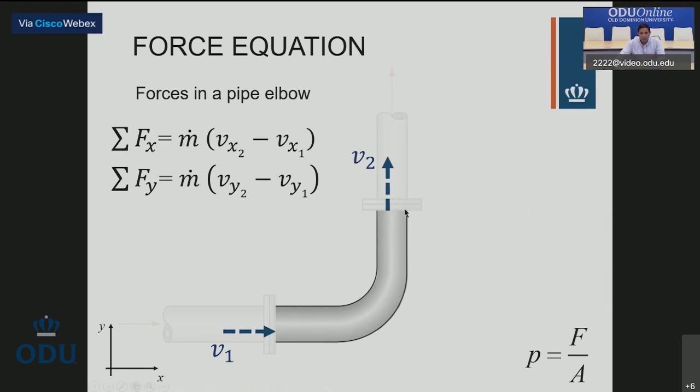And if there is pressure, there is force. So at these points, at the inlet and at the outlet, I have a pressure. If I have a pressure, I must have a force. So the pressure at 1 produces a force at 1. Force at 1 is equal to pressure 1 times area 1, and similarly for this one. But now it's acting downward, opposite to the velocity. Why? Because it's acting upon a surface, a hypothetical surface, I must say.